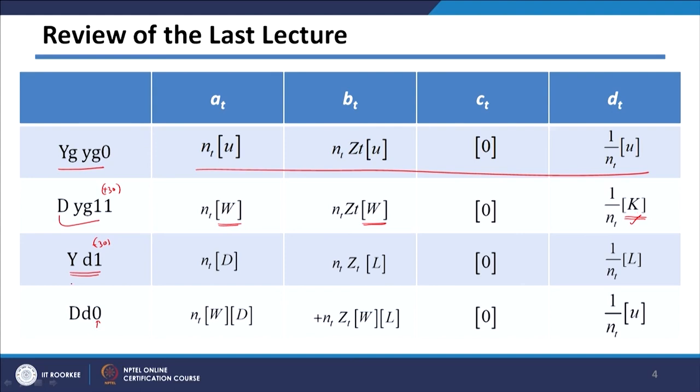In the ungrounded Y delta connection, we need on the low voltage side one conversion, that is line to neutral voltages to line voltages, and that is done by your D matrix here. Similarly, we need current conversion, and that is represented by L matrix, where line currents need to be converted into delta phase currents.